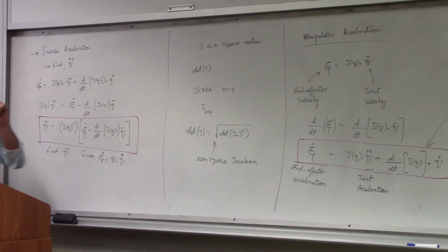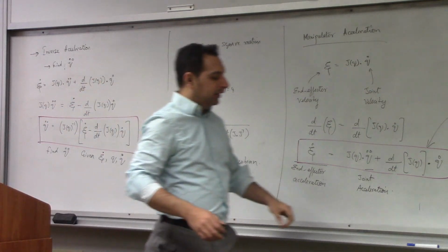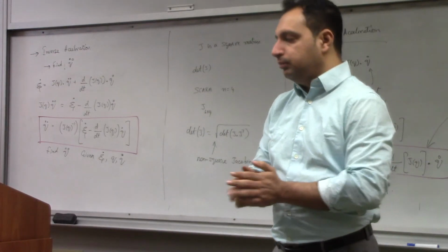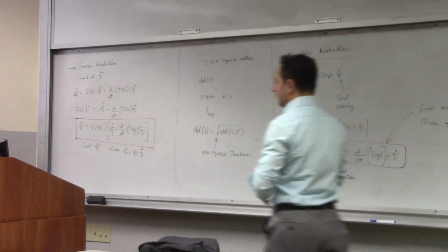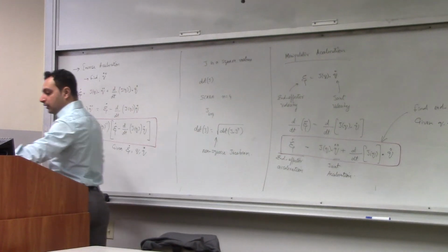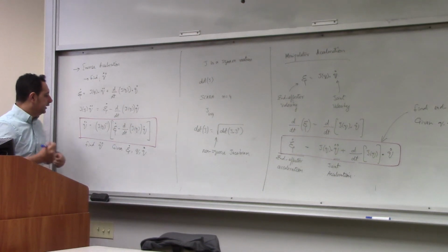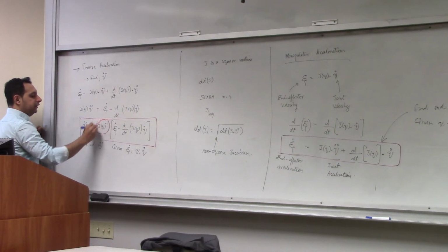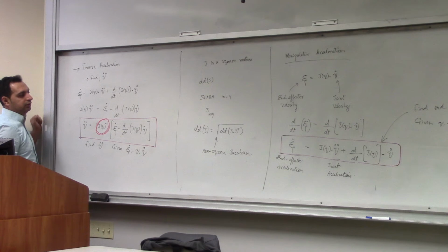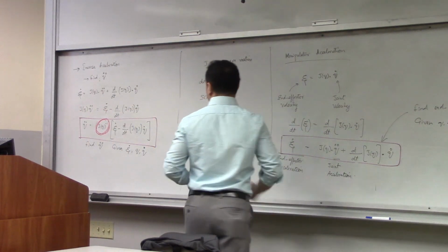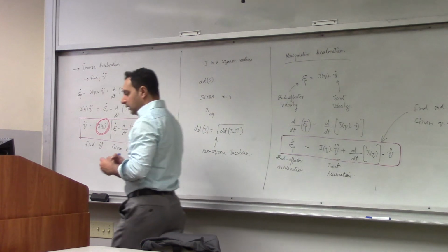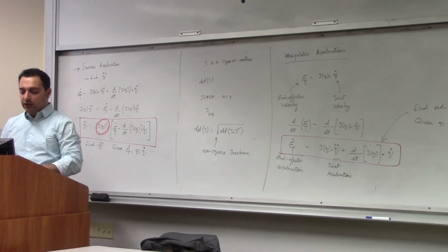These are simple matrices. Obviously, you don't do this by hand. Most of this is programmed so that you can compute the accelerations and everything. The only problem is here, and I'll talk about this in detail. Again, computing the inverse is not possible when the rank drops below full rank, because the determinant will be 0. You won't get an inverse. So we do what is called a pseudo inverse. We'll talk about it in the coming class.